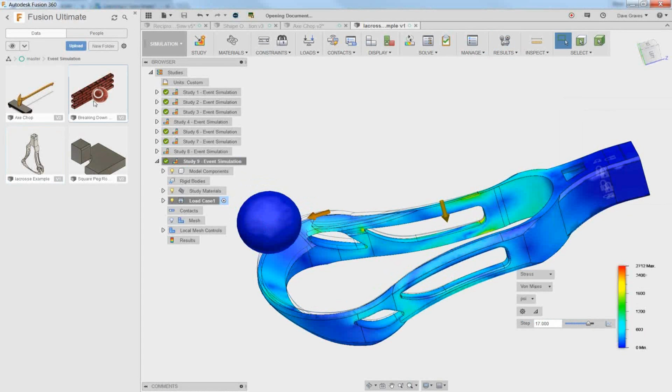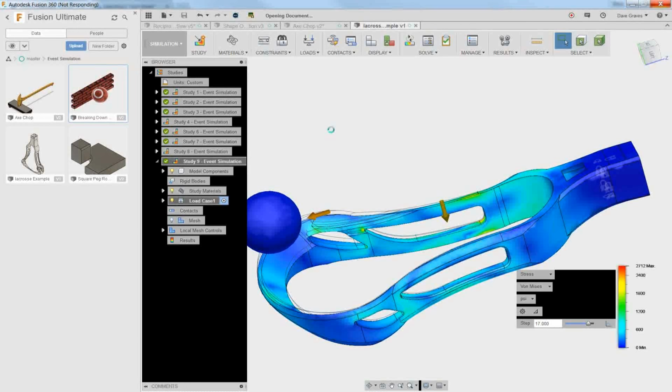And again, here's the wall going through again. So the process is going to be the same. You can do initial velocities of parts. You can just do force. You can, again, have a rigid body for a floor that's going to get hit, so things like drop tests. This is a force fitting. It supports linear and nonlinear materials. So for some of those gasket type things, you actually want to see things compress over a quick period. Just some neat, powerful things you can do with that.